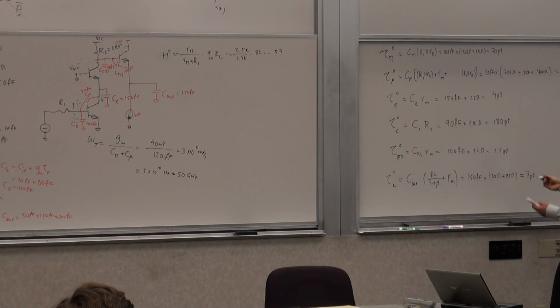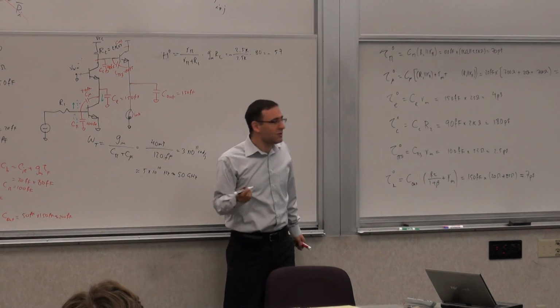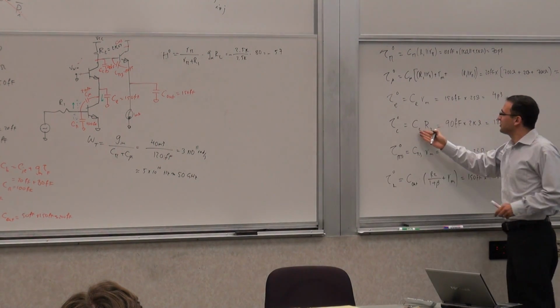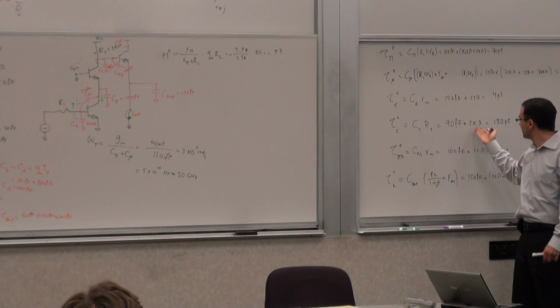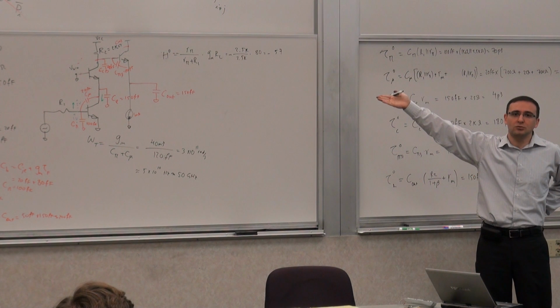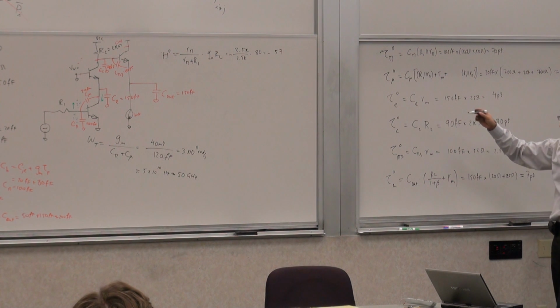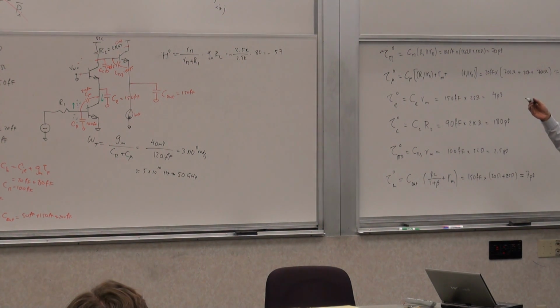So now, where's the culprit? The culprit is here. It's smaller. It's a smaller culprit, but still, this is going to be the limiting factor. And what is causing that, really? You see, you're getting closer and closer to some intrinsic capacitance of the transistor and the resistor that you use there. And you use that resistance because you're trying to get gain. We'll talk a little bit about how we can improve it in a second. But it's becoming more limiting because we have to use that resistance to get gain, one way or another, right? We'll talk about how we can improve that.